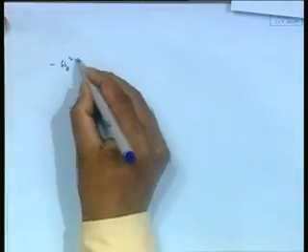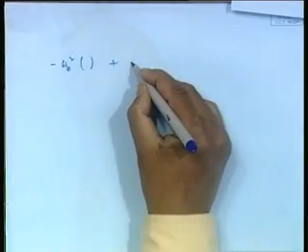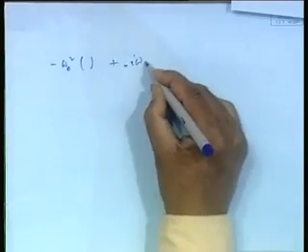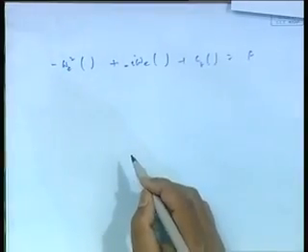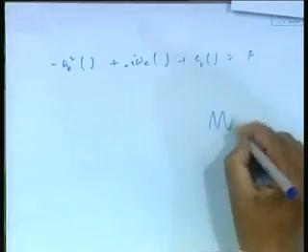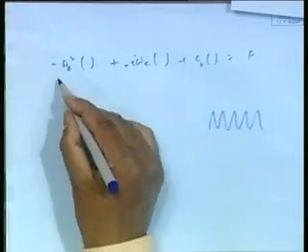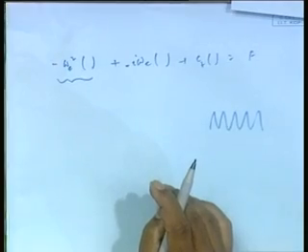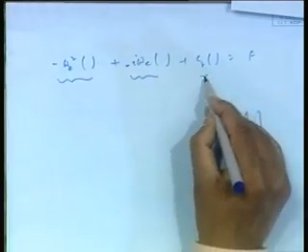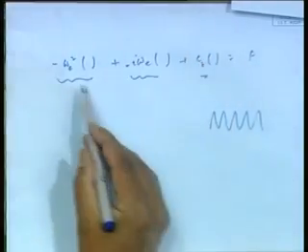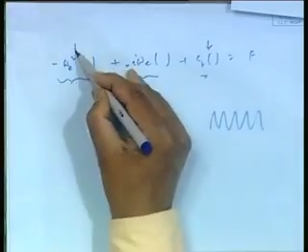Now, here again if I look at this equation, see it was omega e square into something, that is my inertia force, plus I omega, see it is minus here, into something, plus C z into something, equal to force. Now, you see when omega is very high, okay, high frequency, motion is very fast, what happens? This becomes a much more dominating force. This also becomes a fairly dominating force. This becomes comparatively less important. So, what happens is that it becomes inertia dominated, and you will find that the force of this and the force of this are opposite in sign.